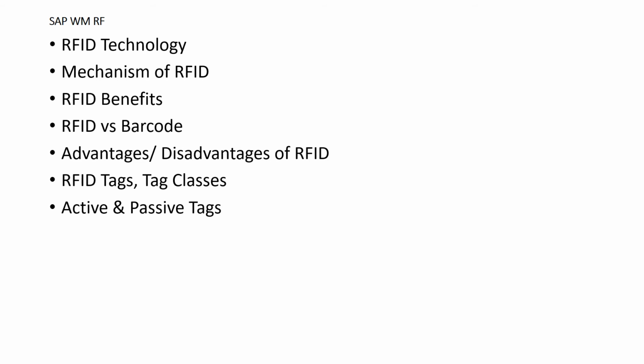Semi-passive or battery-assisted tags have built-in batteries and therefore do not require energy from the reader field to power the chip. This allows them to function with lower signal power levels, resulting in greater communication distance of up to 500 meters. Distance is limited mainly because the tag does not have an integrated transmitter and still must use the reader field to communicate back to the reader.